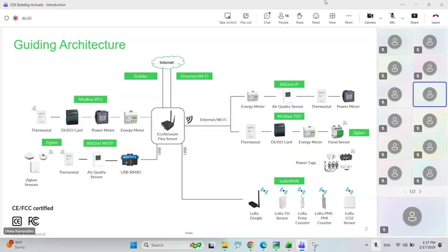Wherever there are limitations in the customer's cybersecurity policy, where clients are not allowing us to connect with the network, we can select the Flux server gateways accordingly. On the downside, for the device segments, each Flux server has a limitation of 500 register points maximum. And it can support 50 devices, for one Flux server that I'm talking about, with all communication protocols combined.